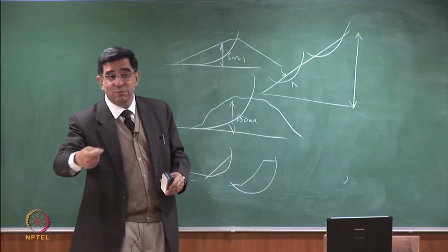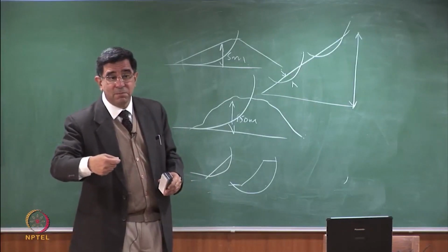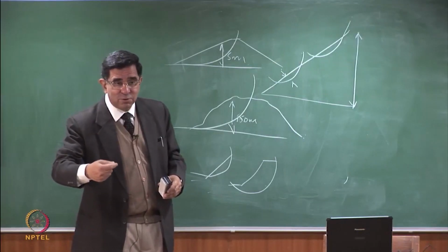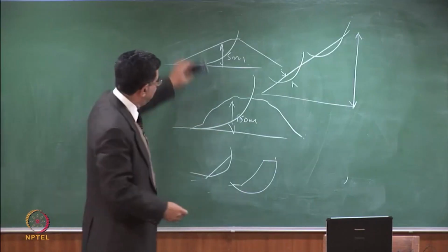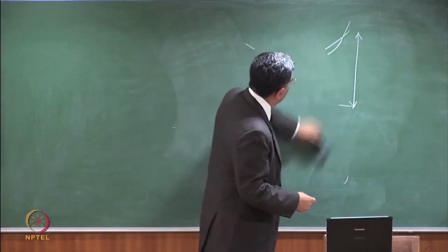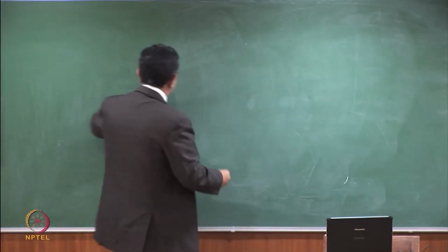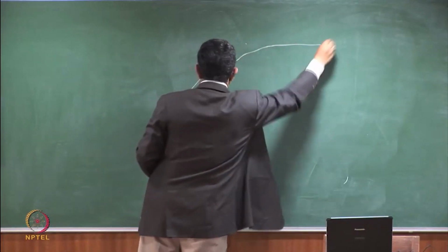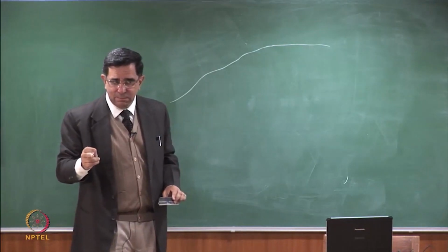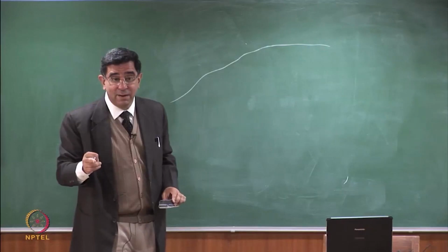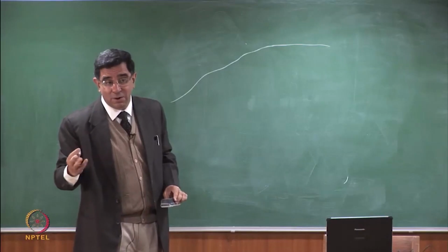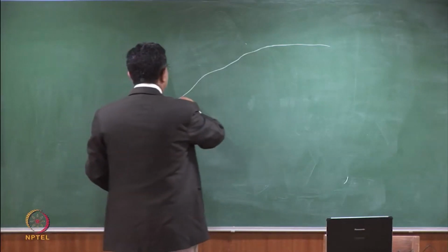So why is it that natural slopes become infinite and man-made slopes don't become infinite so easily? I'll come back to this natural slope, and we are doing a landslide problem. So we talked about 150 meter high. What makes this slope infinite is the fact that the thickness of the soil is very less. After that there is rock. So therefore your soil is like this.